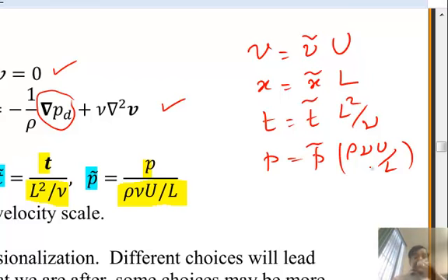Now, this is sometimes called a naive scale analysis because we are assuming that the velocity scale is the same in all three directions. That is not true. So later on, when we do the boundary layer theory, we will realize that we need to actually refine the scales in a little bit more detail. And that was done by Prandtl. But this is basically Stokes analysis for Stokes flow past a cylinder, past a sphere, etc. This result is extremely useful. I'm sure you have all used it in undergraduate classes where you're determining the settling velocity of a particle or the rise velocity of a bubble.